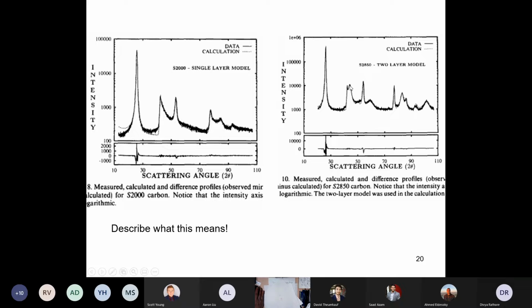If the stacking were perfect without any turbostratic misalignment, this second peak would be sharp and the first peak would be sharp, and there would be another little peak that would appear right there, and this peak would sharpen up as well. So this graphite probably has something like 10% of its adjacent layers in turbostratic misalignment, and the other 90% are stacked AB roughly. So it's really fascinating the way the diffraction pattern changes and the way the carbon structure changes.